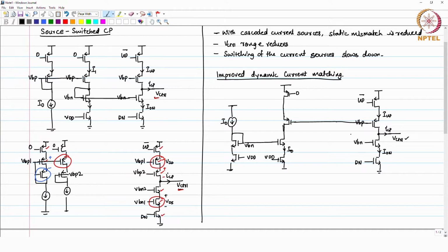The method to do that is that you tap this V control voltage, buffer it, and in the current biasing branch itself you try to force this voltage also as V control. If I call this voltage VCP, the charge pump biasing voltage, then VCP should be equal to V control in the regular operation.